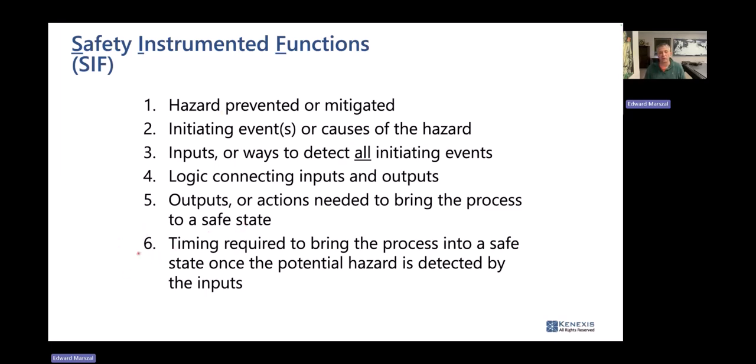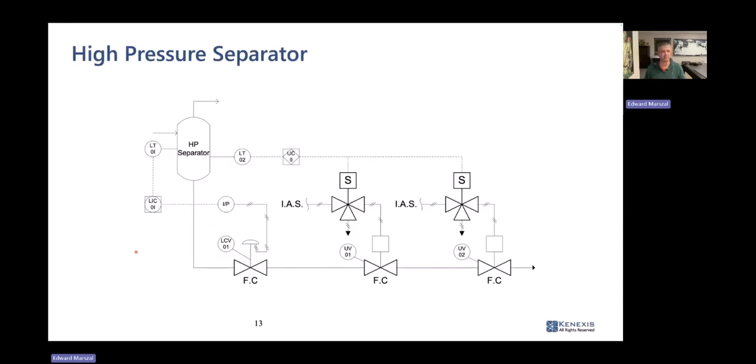And finally, we're going to define the amount of time that's required to get to that safe state. So we're setting a maximum amount of time that the SIF has to be able to complete the actions that it's taking.